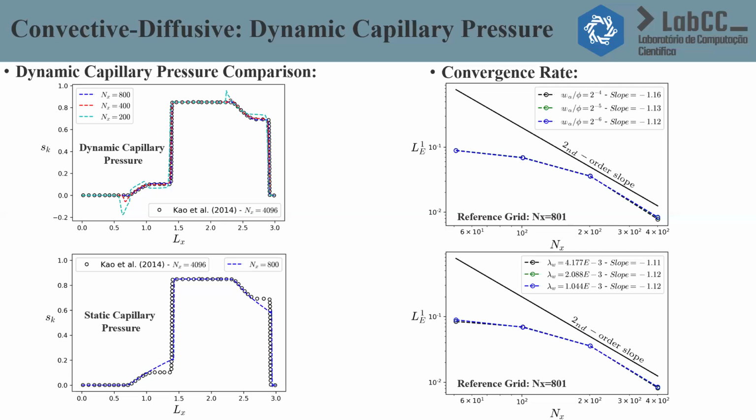I am still comparing the saturation profiles. I just put here a comparison of the effect of the dynamic capillary pressure against the static capillary pressure, to compare the effects and demonstrate that the model correctly recovers the effects of the dynamic capillary pressure.